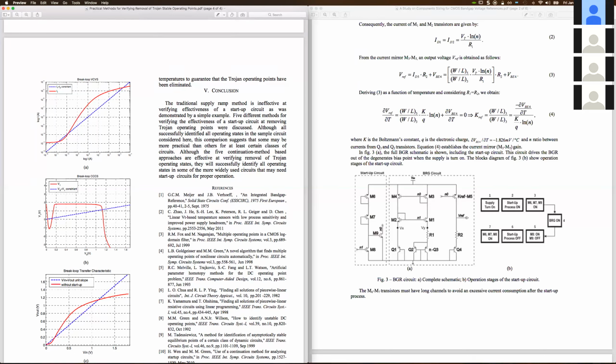I want to use RW resistor in my design, but whenever I place this resistor in my simulation, my transient simulations won't run. It doesn't give me any error, but the initial transient simulation shows me NAN.